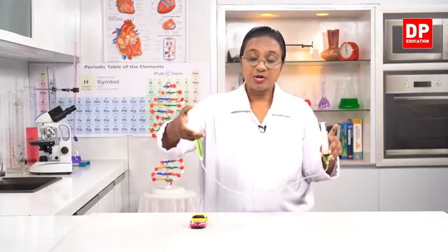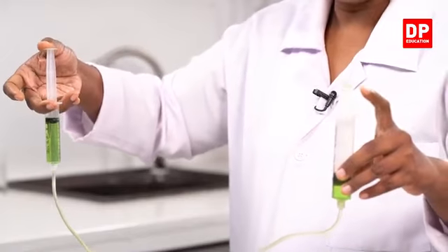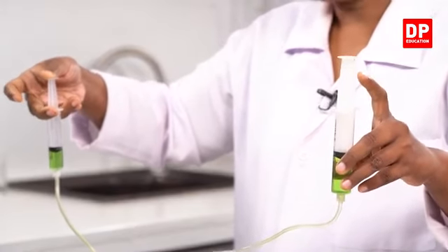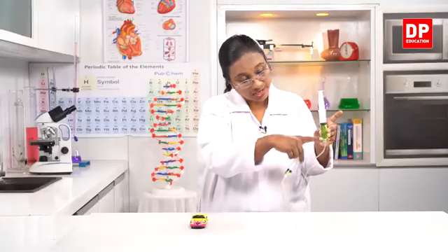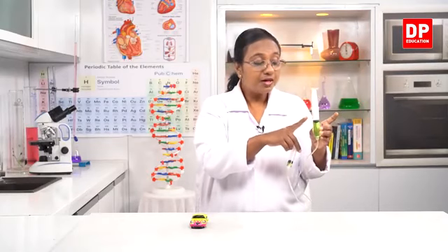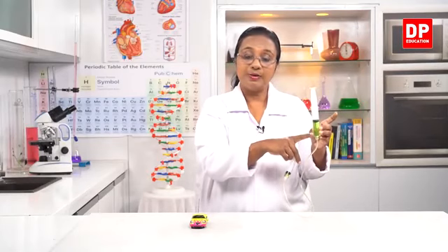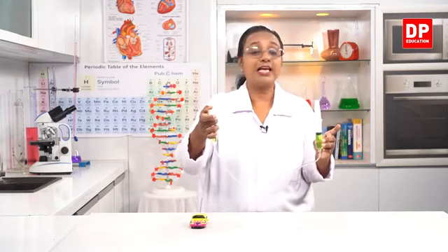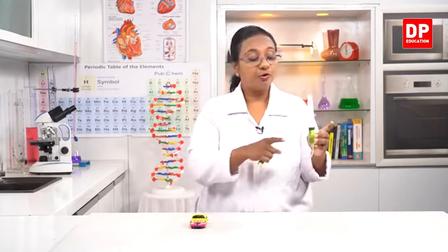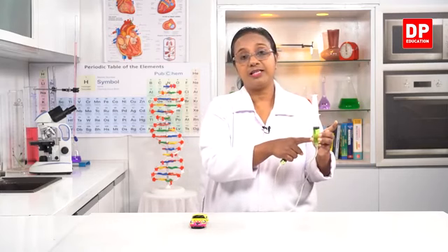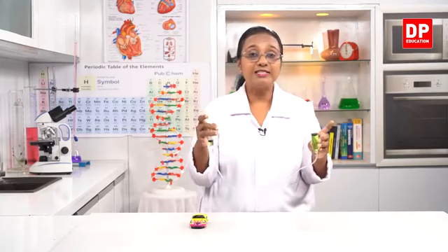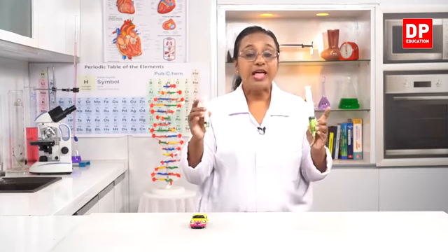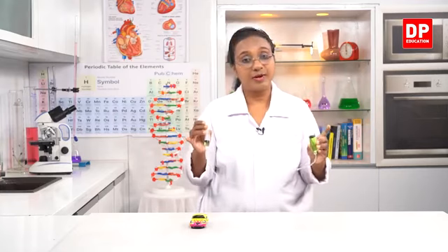So here again I'll demonstrate. When we push this piston, you can see the large piston rising up. So the pressure is being transmitted through the liquid. And also there is a liquid column here. Compared to the pressure exerted by this liquid column, the pressure by the force I apply is greater. Therefore, we neglect the pressure exerted by this liquid column in the large piston as well as the small piston. We only consider the pressure exerted by us by exerting a force. So that concept is the hydraulic press.